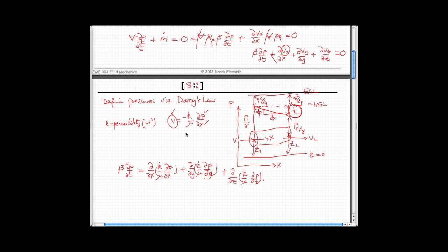You double the velocity, you double the frictional loss. And so that's perfectly adequate for porous media flows, because in these cases, basically the term v squared over 2g is much, much smaller than the other terms for pressure and for elevation. I suppose you could write these together. Or changes in the velocities. So the velocities will be very small, so changes in the velocities can only be small, and the magnitudes of pressures in the system are also similarly small.